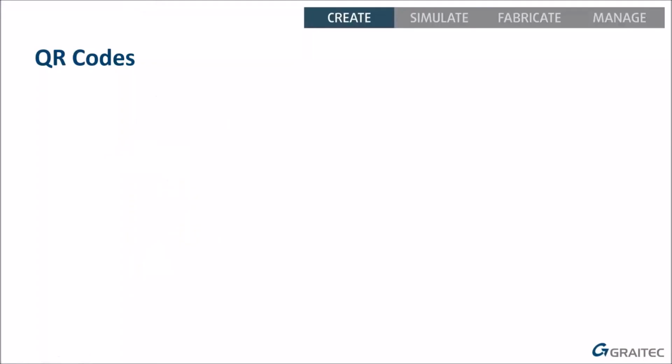So the last little bit that we're going to look at is QR codes, because this is fine if you remember to put the link in an email. Let's say it was your site team, they want to check something in the 3D model. Well, if you don't email them or send it to them in a text message or WhatsApp or whatever, they won't have a link to that model. But on site, they probably have the GA drawings printed off with them. So what we can do is put a QR code onto our GA drawing that will then link to the model.